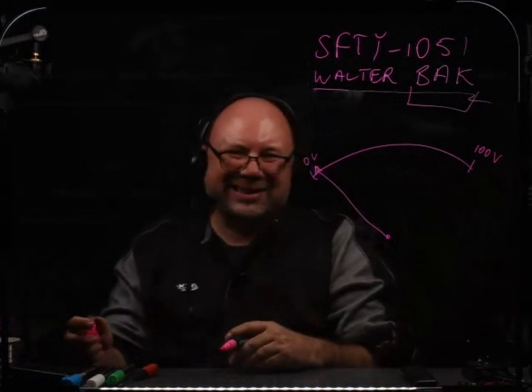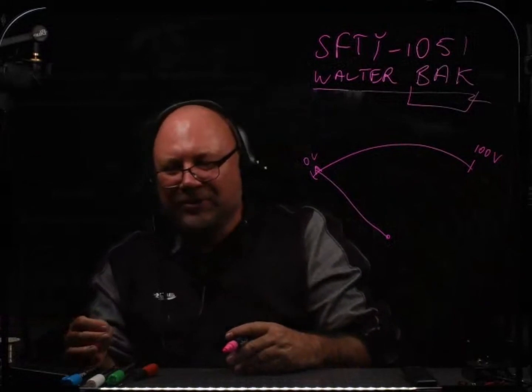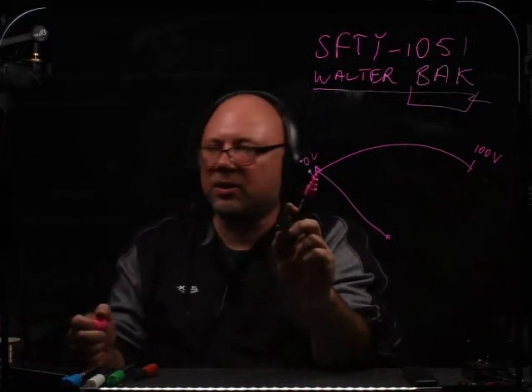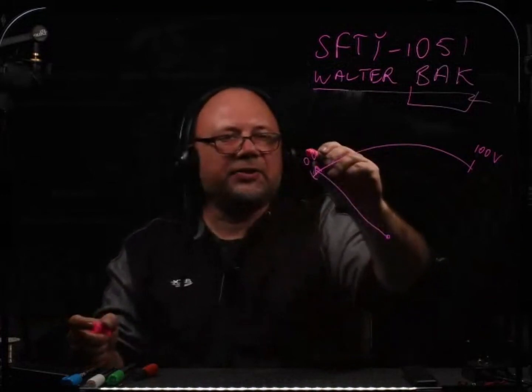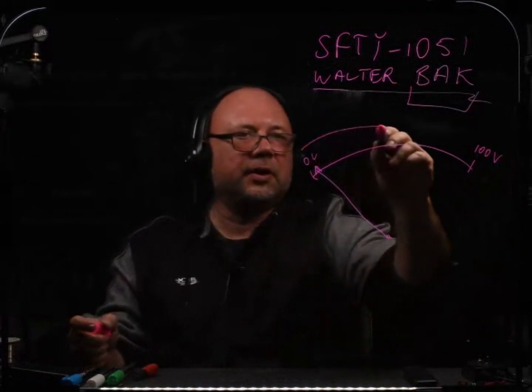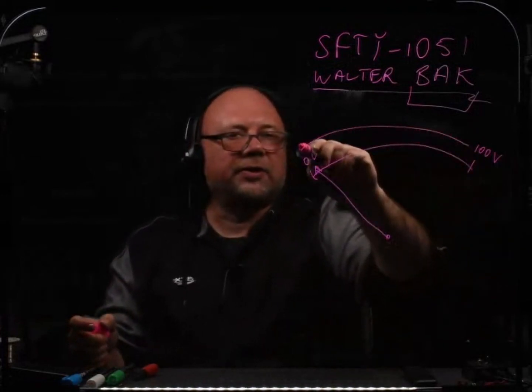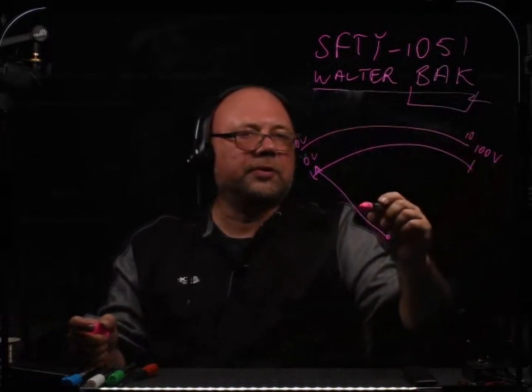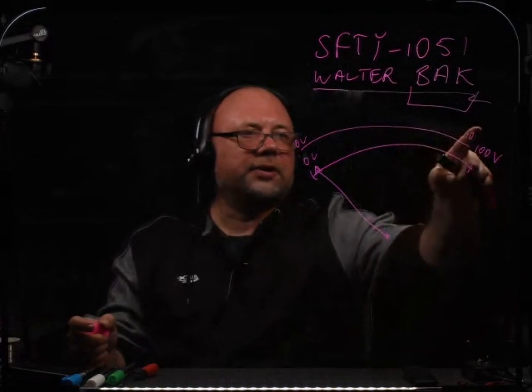Now you're going to see, is this 3.5 volts or is it 3.6 volts? It's not going to cut it. It's just going to say it's a very low voltage. But if you had another scale, you switch the range, another range. Let's say this one is from 0 volts up to 10 volts. Okay? Or let's say up to 5 volts, if there's one like that.